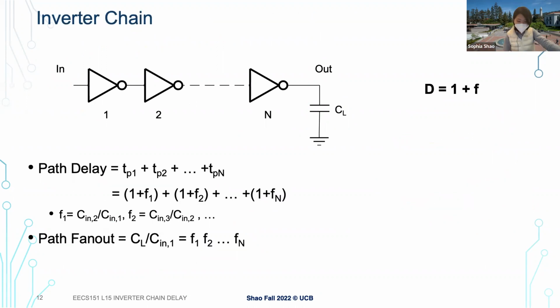Oh, right. So the reason I add n, we basically start from here, right? We just put all the ones to the front. There are a bunch of 1s, and then a bunch of f1 plus f2. We just separate the one part, the constant part, and those ones I wrote turn into an n. So basically all the parasitic delay added together becomes a constant. Yeah, so that's where n is coming from.